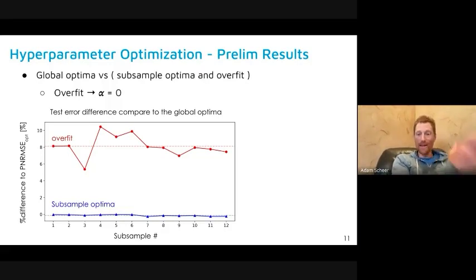In other words, you're using a net of zero, which is exactly that situation. So we wind up with CVRMSE values for solar PV customers that just absolutely blow up. And one of the biggest reasons we're here in the first place, doing this new hourly model development, is to make sure that the hourly model can perform well for solar PV customers. The existing CalTRACK 2.0 model does not perform very well for solar PV customers because it's not aware of solar irradiance data for one, and we're using metrics like the CVRMSE that don't actually give us a lot of insight in comparison to non-solar customers.